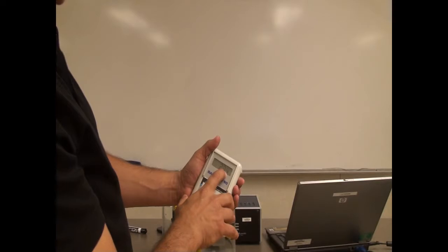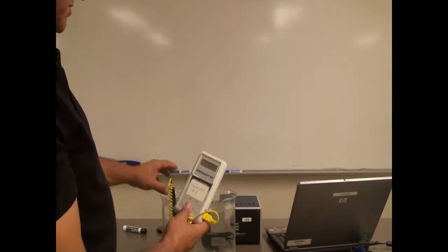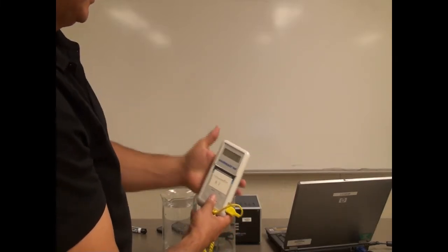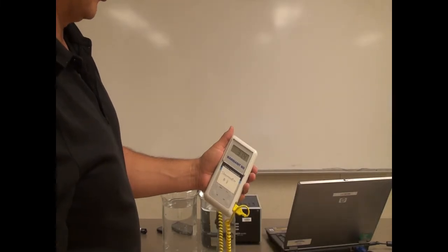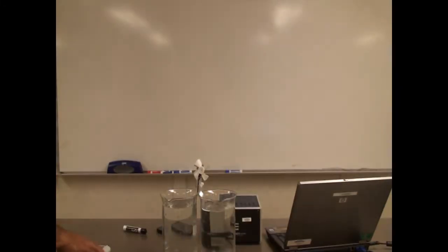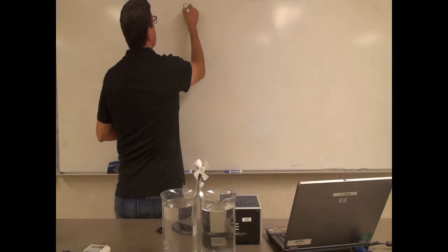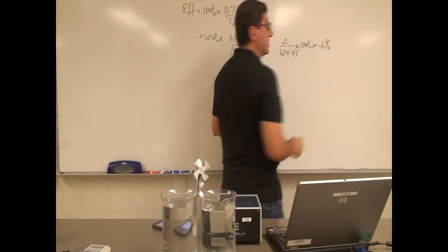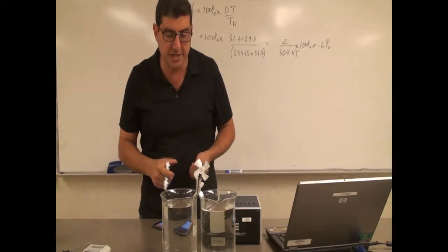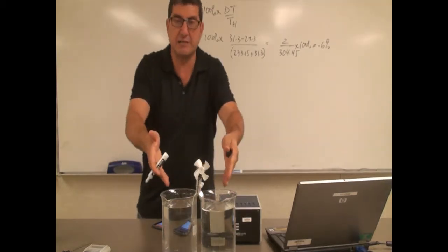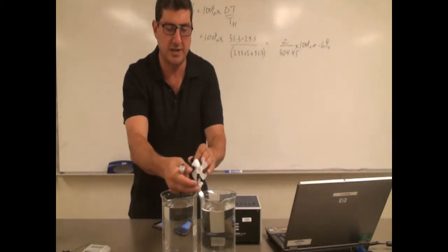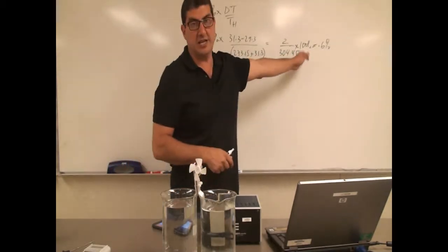The left one is 29.4 Celsius, right? Right now it's dropping to 29.3. The other one is 31.4. 29.3 over 31.4. Okay, so what's the maximum efficiency that it can have? Remember when we had one hot, one cold, we said the efficiency was, I believe, around 20%. Right now it is so inefficient, there is not much temperature difference, 0.6% efficient. In other words, it's so inefficient that it can't even get the wheel running. And that's even the most efficient that it can be.